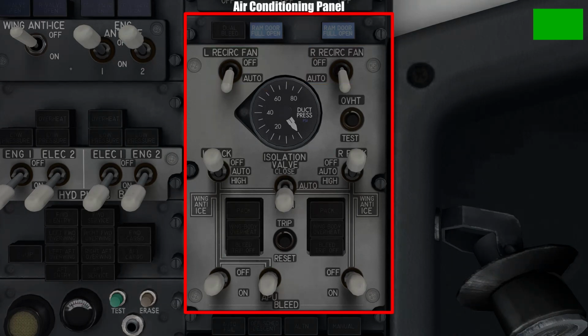Below these switches, in the middle, we have another analog gauge that displays the duct pressure of the 2 feed lines in the recirculation fan systems that carry the air around the aircraft. This little switch is a simple overheat test switch to make sure that the overheat light indicators below are working.